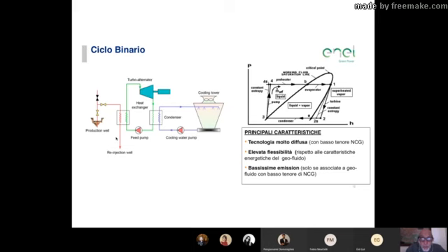Now, the impermeable cover is never really totally impermeable, and in time will allow the gases to come to the surface. Or, since the gases are much more mobile than the water, the gases will flow directly to your production well, and you will produce a short circuit, and you will start producing cold, non-condensable gases very soon. So you have to be very careful: you don't want to have a lot of non-condensable gases in your fluid to use a binary cycle.